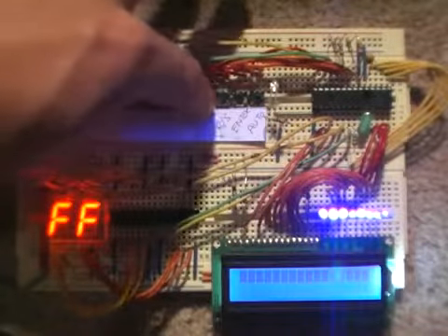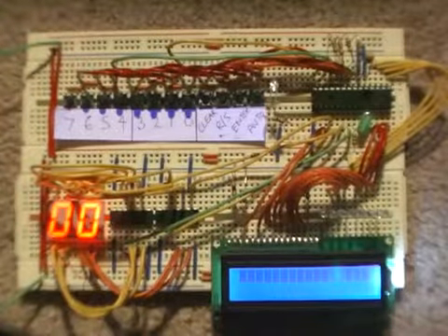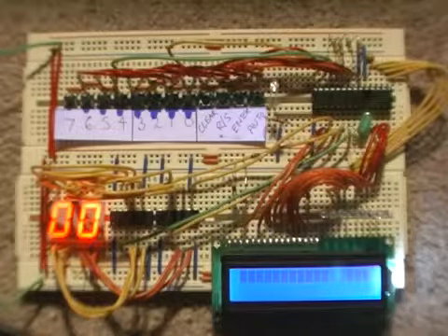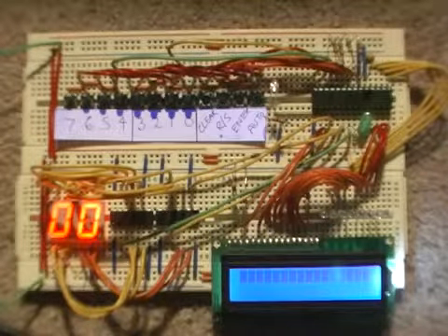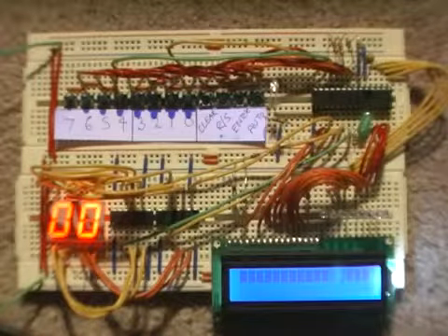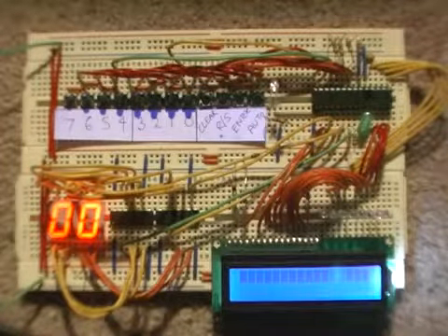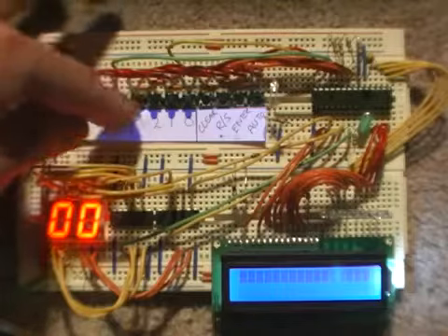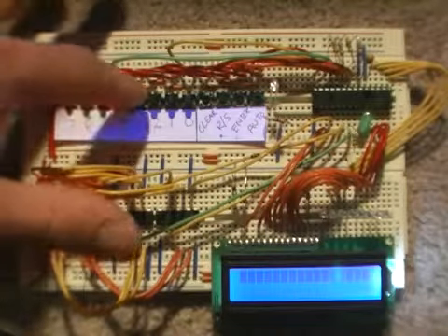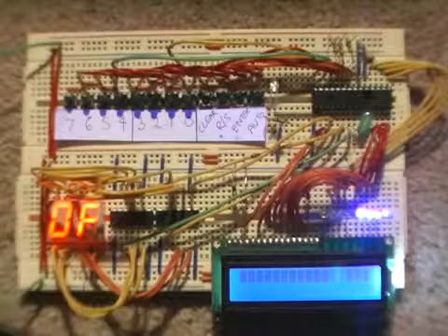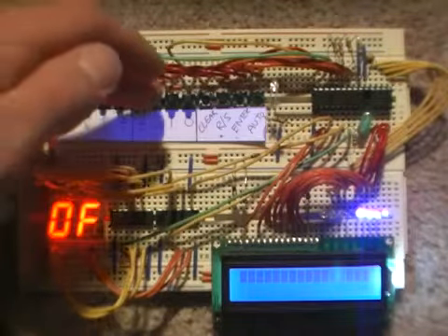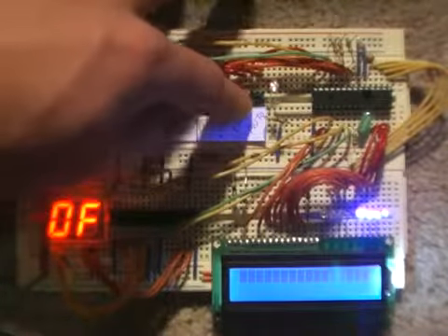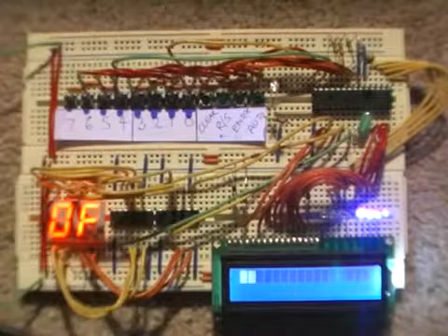That auto switch, what it does, to initialize the LCD you have to turn the display on by entering a code and setting it to what mode you want it in. For example, 2-line mode, single line mode, how many pixels you want it to display, and so on and so forth. So the code to turn the display on and the cursor on is 0F in hex, or in binary it's 00001111. I'm in command mode. That's what it has to be in. So enter. That's turned the display on.